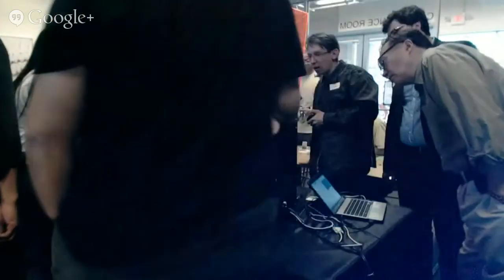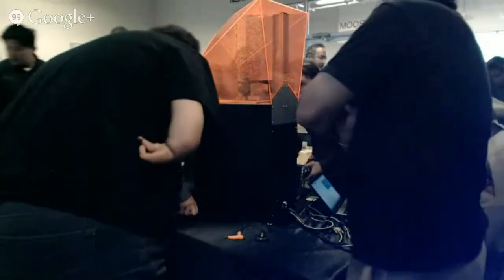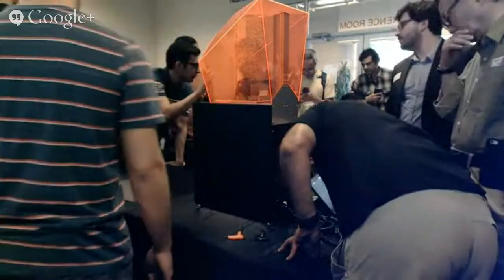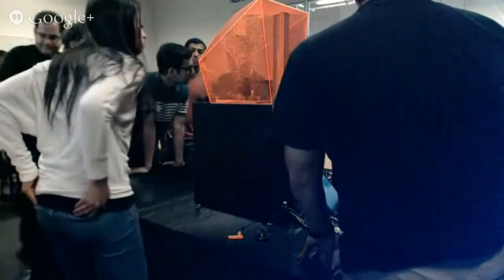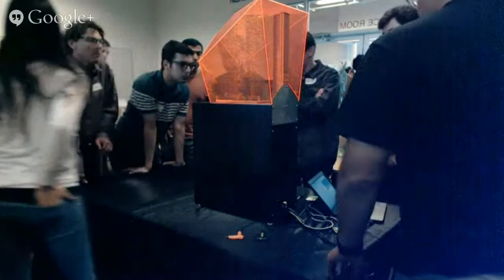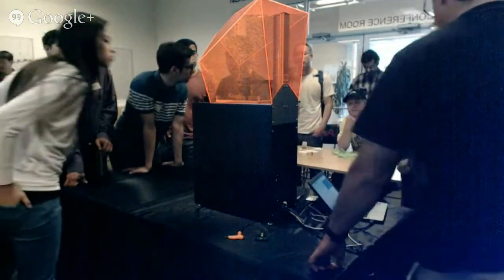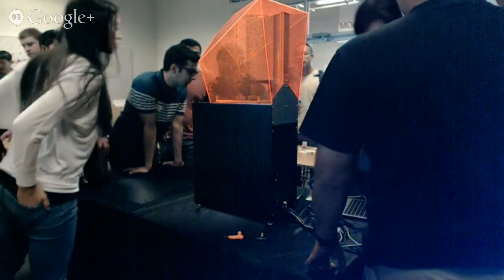And so if you have any uncured resin, you got to make sure to cure it before you throw it away. So for instance, all my scrap parts and everything, I gather them up in clear plastic bags. And before I throw it away, I put the plastic bag outside in the sun for a couple of days. And then it's fine. But generally there is going to be a small amount of resin that ends up going down the drain when you clean up, right? It's all about getting as little resin as possible. Liquid resin in the environment. Solid resin, not so big of a deal. Liquid resin you want to keep out.